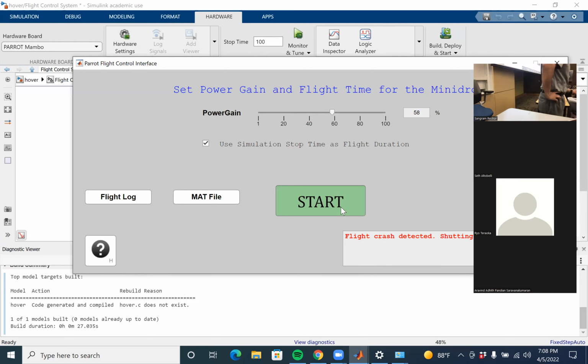So it took off, but it was not stable. Why was it not stable? You don't have hover control. So first you need to implement the hover control, and then once you add this loop to it, you will actually be able to control it to whatever location you want.